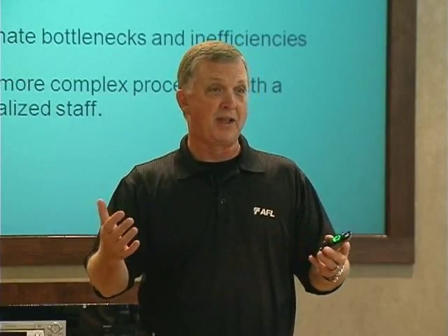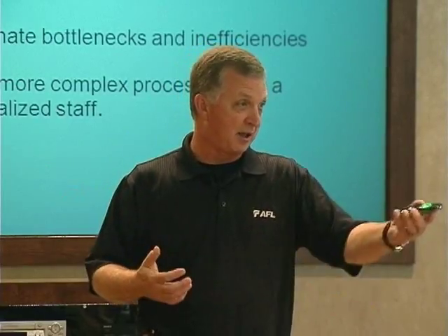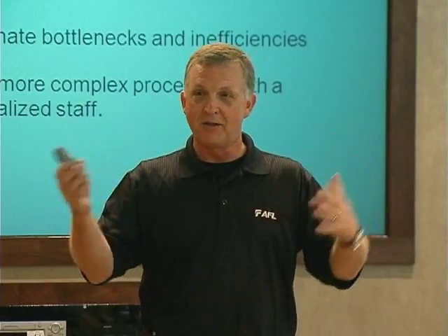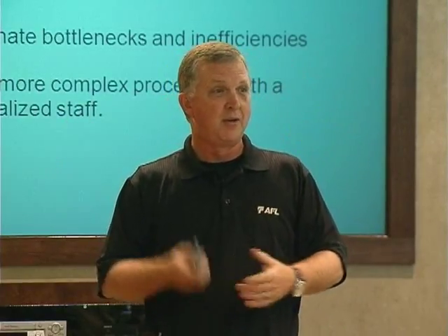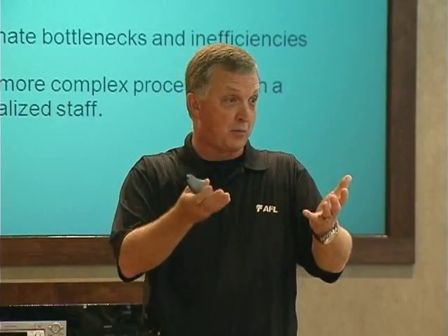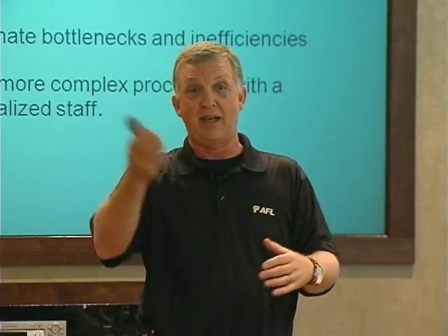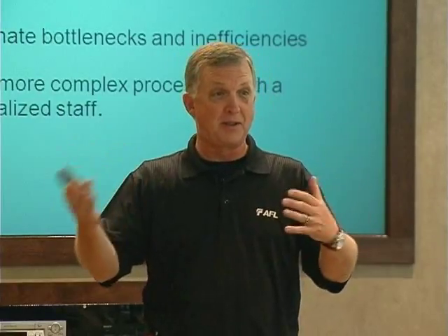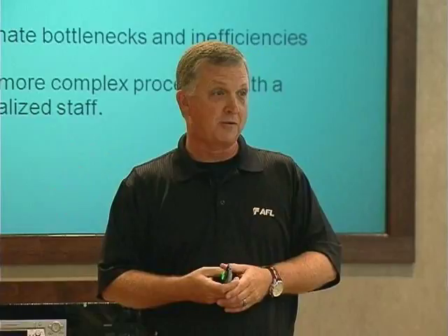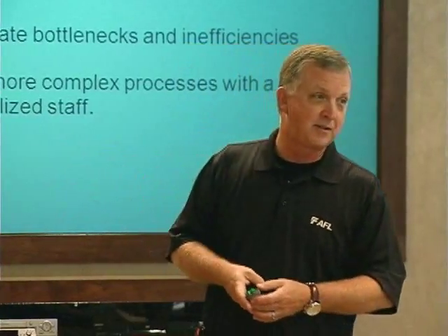So those are very simple things, and then you get into more complicated things like the capacitance and reactance and all the balances between the phases. You see 3 phases on your distribution lines. Well, they need to be balanced for system purposes. So I'd like to know if phase A is pretty close to phase C, and if it gets really out of balance, I need to go out and be doing some changes to the infrastructure. That's the kind of information that these systems will provide. All right? It will give you the instantaneous reading, and you can feed them back into your computer systems, and you measure that over time.